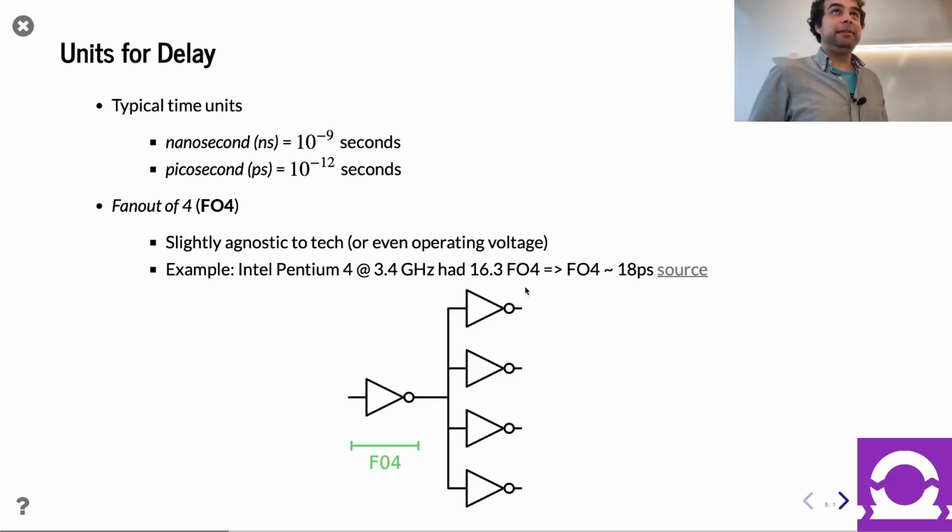But like I said, for us, you need to talk about things. Okay, we talk about how many FO4 this design is, and you kind of appreciate that. Once again, you're probably also good to be skeptical: wait a minute, FO4 supposes your design's been synthesized and actual logic has been chosen. Yes, it's not something you can just look at in Chisel and tell right away, but these are just units to be aware of. Cool. Questions?